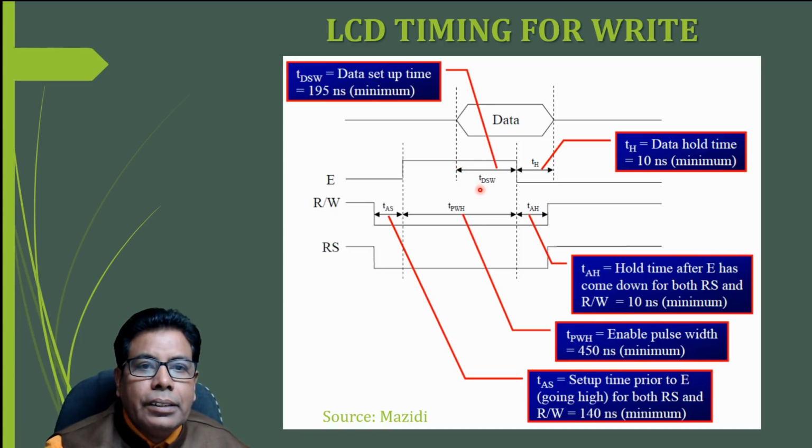So this DSW is the data setup time, that is 195 nanoseconds. So during this time only the data can be written onto the LCD.